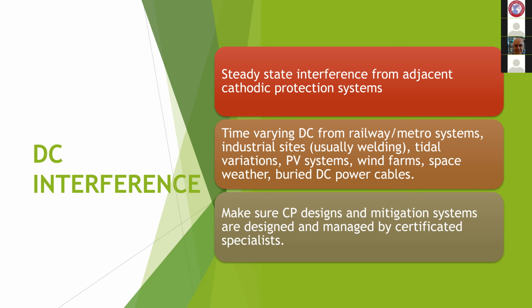But if it happens to be close to another pipeline that's 50 years old and needs a lot of current and has big anode ground beds in the ground, the voltage gradients generated from those existing systems can adversely affect your pipe. Now, if the coating's perfect, it will only be a measurement problem.